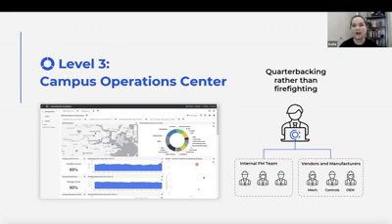I'm not going to do my air handlers quarterly. I'm going to have FDD running on those air handlers, and then I'm going to do them semi-annually when I do a season change. And maybe I only do half my PM tasks because I know that FDD is running and I can trust that what they're giving me is going to find any of these other issues.